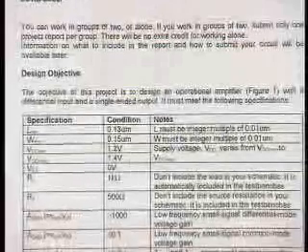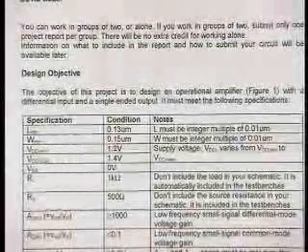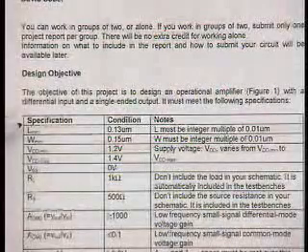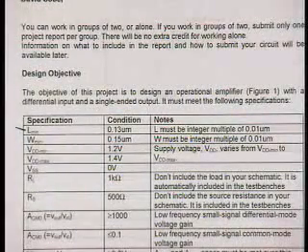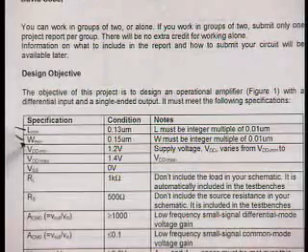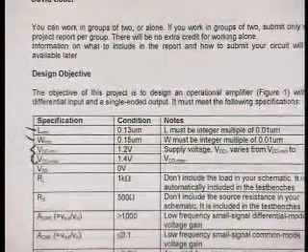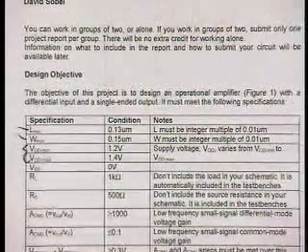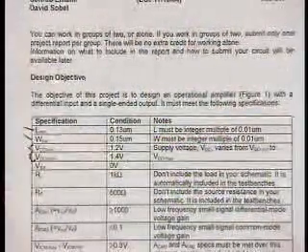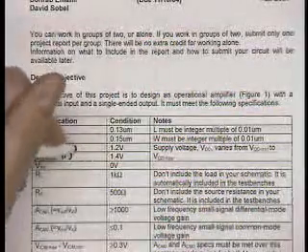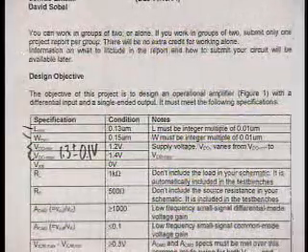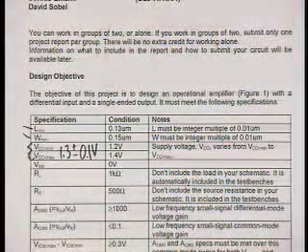Okay, so everyone knows what the project is, and just to go down the design specifications and clarify things. So L-min, W-min, same as before. A difference on this project is that there are now two VDDs over which your circuit needs to operate. And the test bench processing will do that. So it's basically VDD is 1.3 plus or minus 0.1 volts. So 1.2 and 1.4 volts are the supply voltages that we test over.